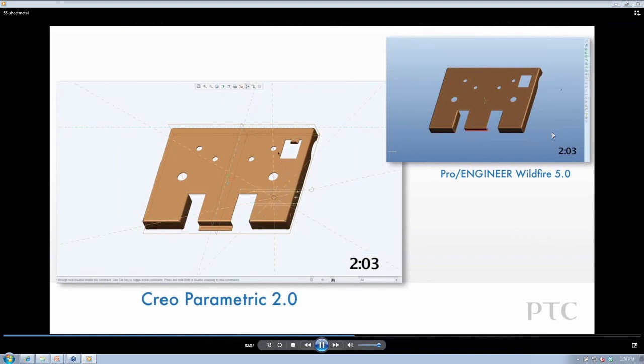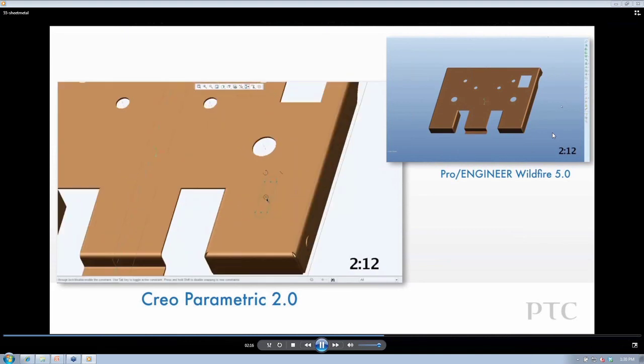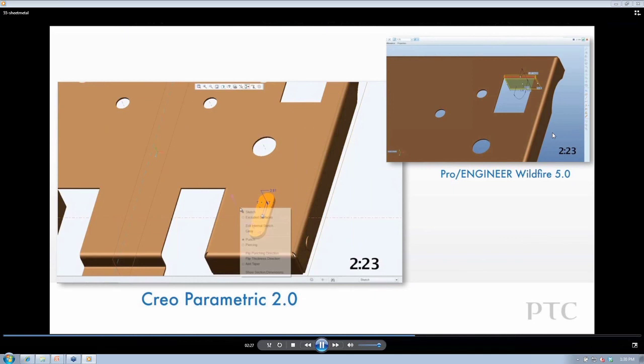And then you can put it where you wish to, rotate it, resize it, and then you'll see a little preview of this little form. And then you can control what you want it to look like, which direction to go in or out for the stamping. Again, no second tool for this. You can do it all on the fly. You can add extrude or add draft at the same time, add some taper, add your rounds.